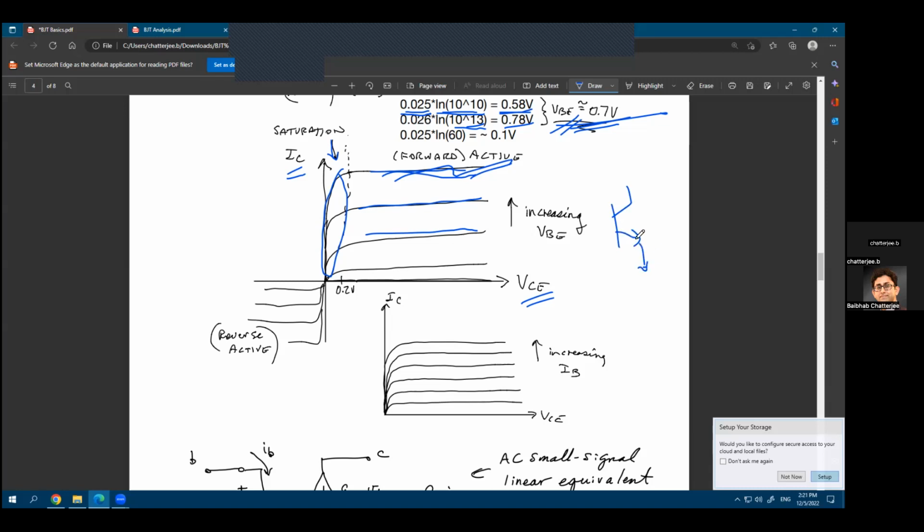So I am emitting my carriers. So in this case, it's done. So this is the emitter, right? For NPN type BJT. And this is the direction of the current, which means the emission of the carriers is happening on the other direction. It's an NPN BJT. So the majority carriers are the electrons. So electron flow is in the other direction of the arrow. So electrons are flowing inside the base and then towards the collector.